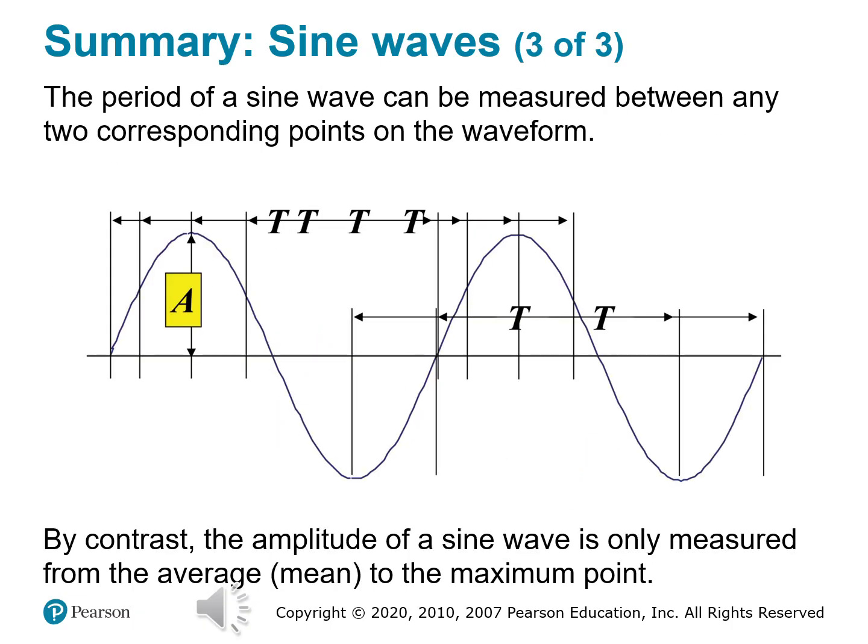Measuring the beat, amplitude and period in action. So we've defined amplitude and period, and now it's time to see how they play out across a full waveform. On this slide, we can observe two main ideas. First, the period, denoted by capital T, of a sine wave can be measured between any two matching points on the waveform. And that could be peak to peak, zero crossing to zero crossing, or any repeating spot as long as it defines a full cycle. The period tells us how long one wave cycle takes.